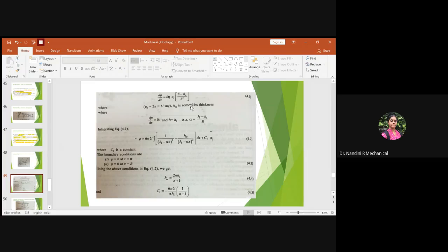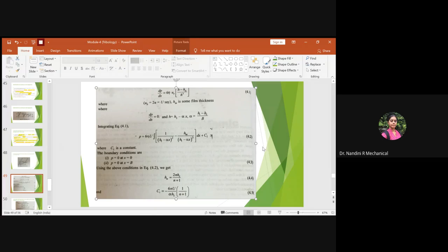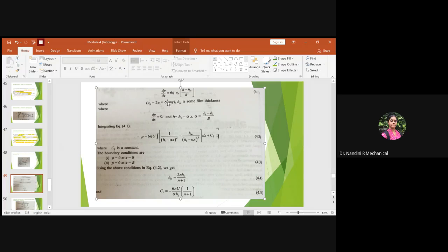So with this aspect, if you remember, the Reynolds equation was given with respect to variation of the pressure, right? So here dP by dx will be equal to 6 mu U suffix b into (h minus h suffix m) divided by h cube. So this is a lengthier derivation. Sometimes they ask and sometimes you get a problem. So kindly do understand and write. If you write fully, you will get full marks.